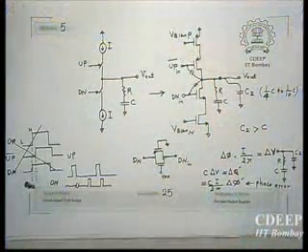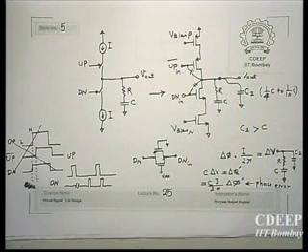So this phase error should be controlled by just using appropriate current sources. Another problem that exists here, and this is a common problem, is that if you use a switch in the path of a current source, usually it is not a correct way of doing this. Or if you do, you should be very careful to handle the current source when the switch is off. Because as soon as this upper switch or lower switch is off, the current source cannot conduct. That means that your current source will be off.